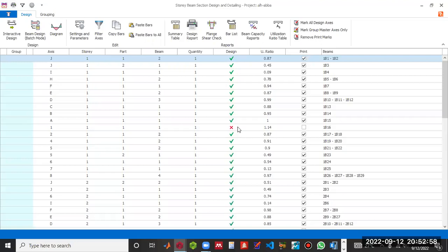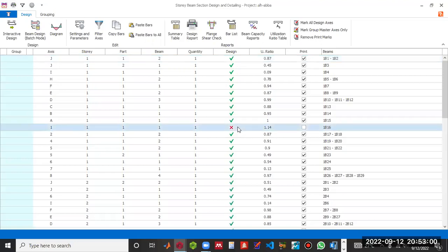But when you see an X here, it means that maybe the thickness of the member is not enough to satisfy the deflection, or there is too much reinforcement, or the reinforcement that the software adopts does not reach the requirement for the member to be safe in deflection and so on.